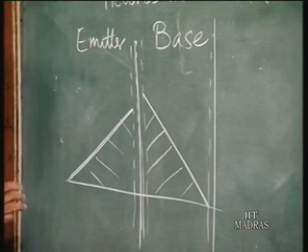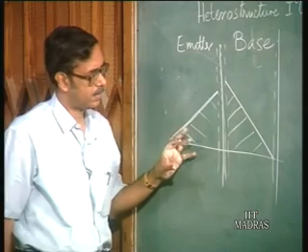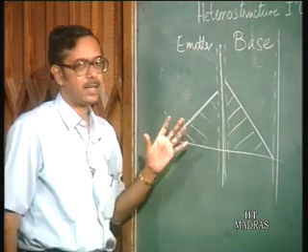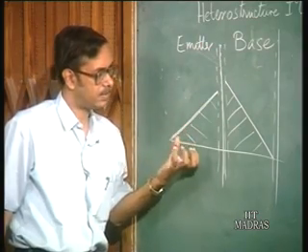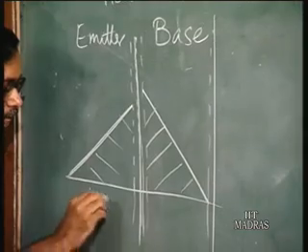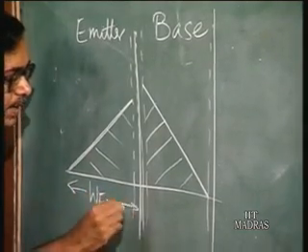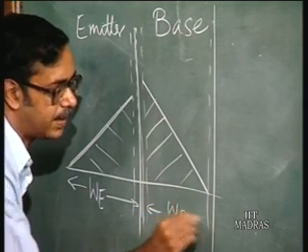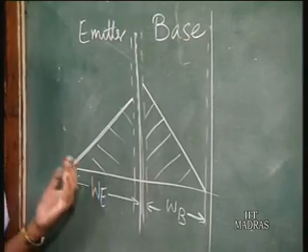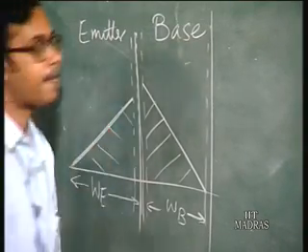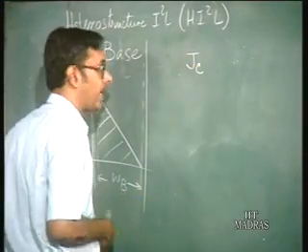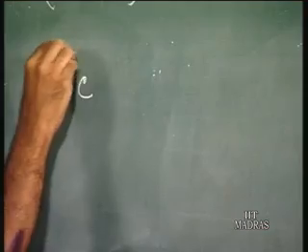Now, if we neglect the recombination in the base, we can write an approximate relation for the beta of the transistor. So, this is, say, the emitter width, from here to here, and this is the base width WB. WE is the emitter width and WB is the base width. Now, what is the collector current approximately? Say I am writing the collector current, IC is equal to